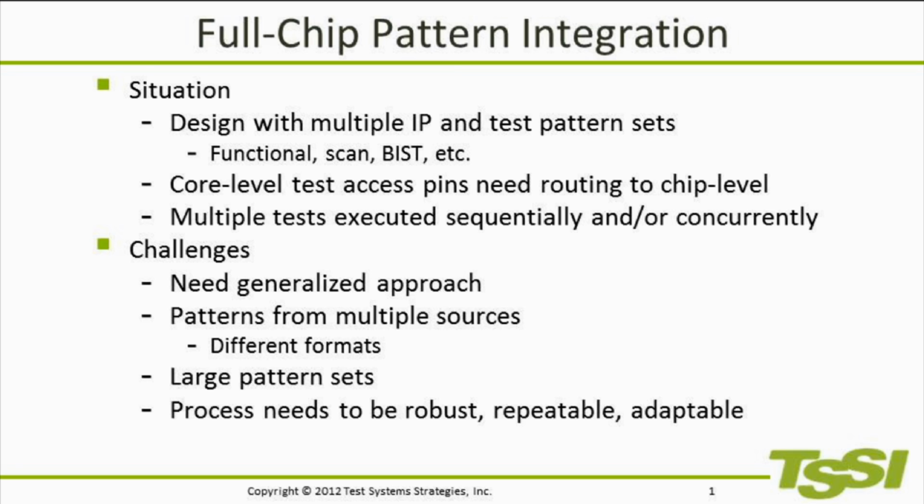This is an introduction and demonstration of the full chip pattern integration solution from TSSI. Full chip pattern integration refers to those designs that have multiple test pattern sets that will need to be conditioned and combined. This commonly occurs with designs that have multiple IP blocks. It's usually necessary to route test pins to the chip level. Test patterns will need to be merged to execute sequentially or concurrently.